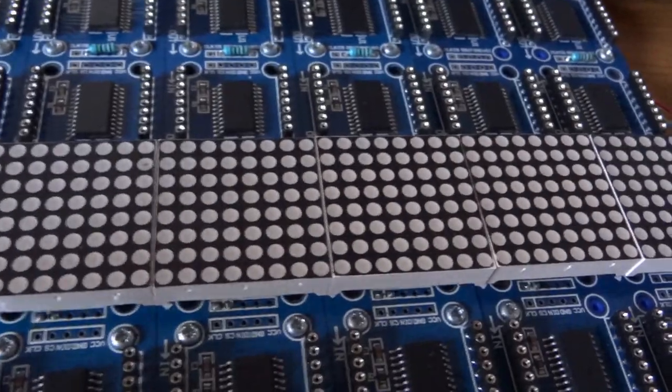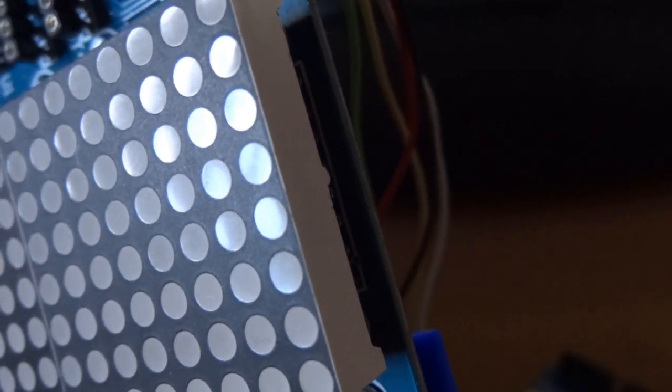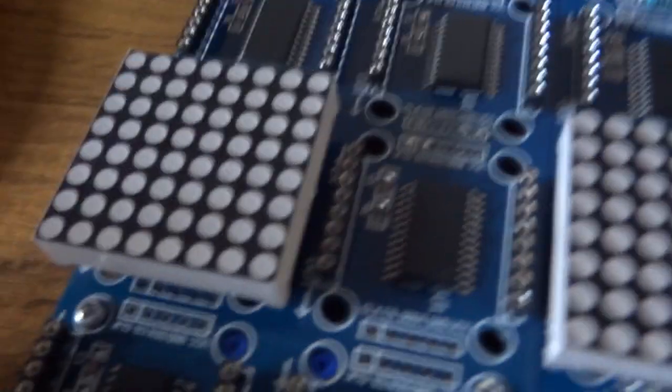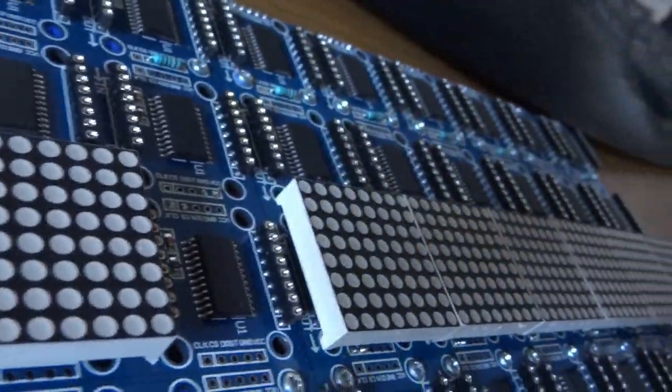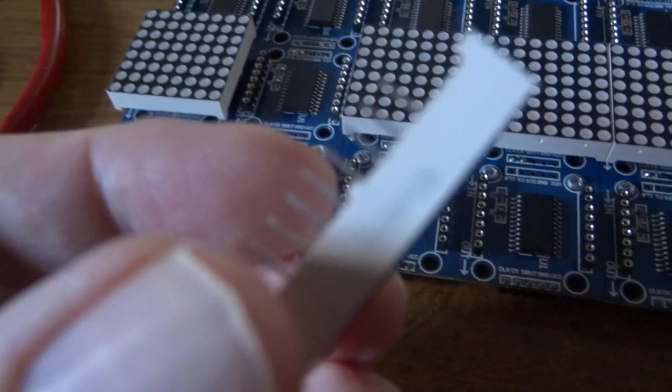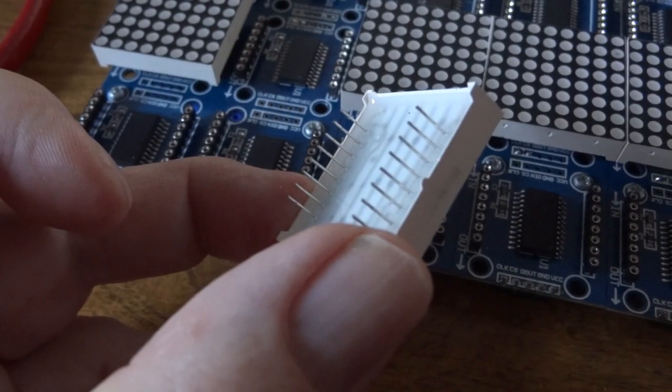And if you're making one of these and you're doing it in the orientation that I've done it in, the little marker nipple on each of the 8x8 LED blocks ends up on the right. That's in the centre of the chip. You see there's a little point there in the centre, and there isn't one that side. And there's also usually some marker date writing or something usually on the end with the little ID.